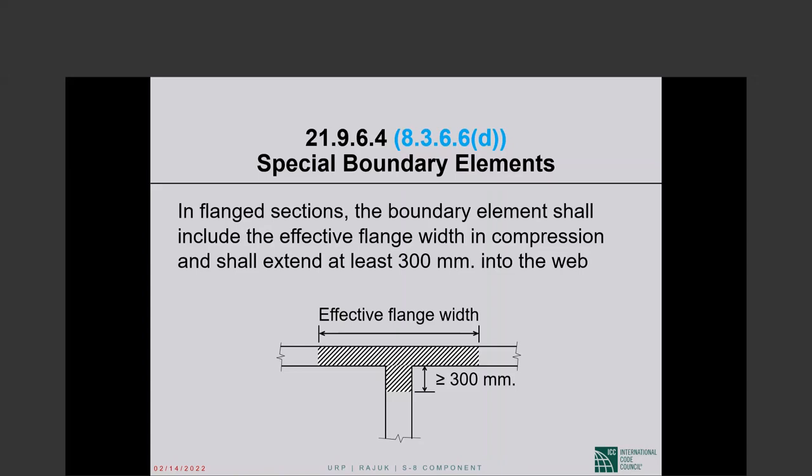And the only time we use story height is in drift check. So in the design of a shear wall, I do not even know where you would need the story height. We use H sub W, which is the total height of the shear wall.